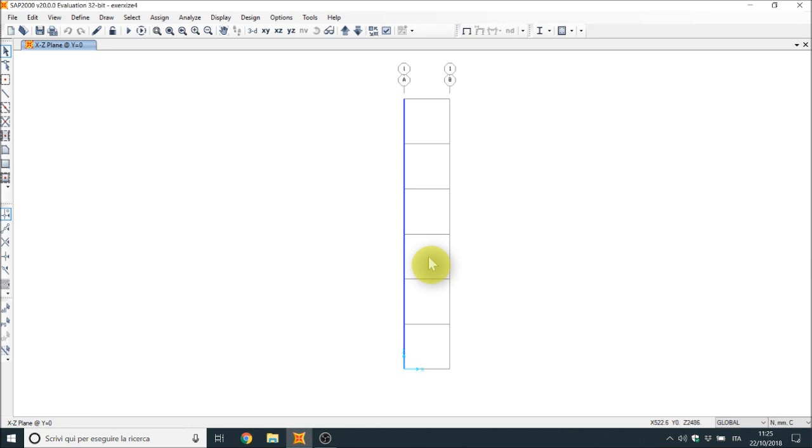But the second option, that is the more commonly used option, together with the third option, you could say put imperfection, but only global imperfection, so no local imperfection. We have global plus local. Here is just global.